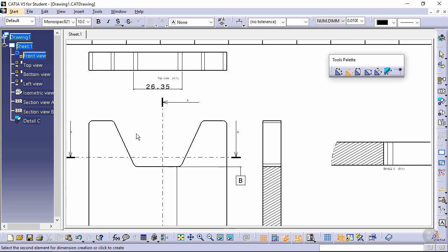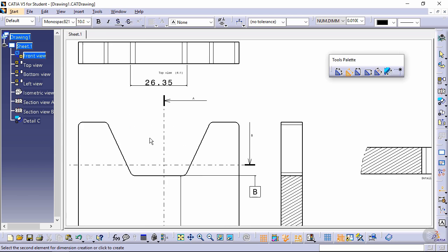And zoom in a little bit on the corners of the front view and select the entities which need radius dimension labels. So here, left click once, the radius dimension appears, and if I move my mouse cursor, I can choose to locate the way the radius dimension looks, and I'm going to make it look this way with a left click, lock that radius dimension position into picture.